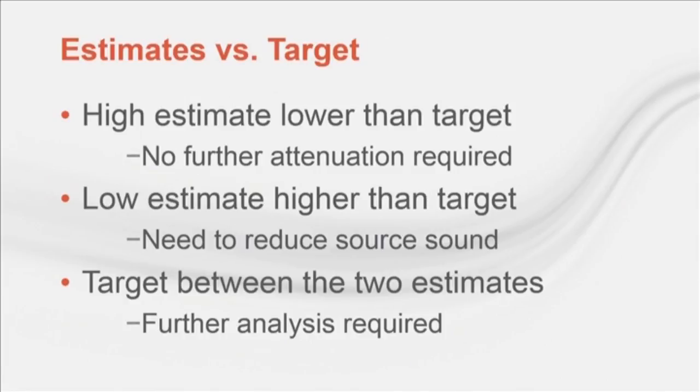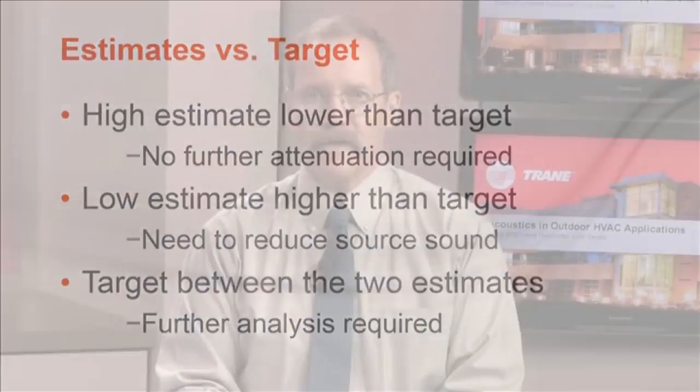In the complicated acoustical environment shown in the original picture, I would want both estimates to be below the target. If that can't be done with simple changes, this level of complication is a good reason for getting an acoustical consultant involved. That makes sense.